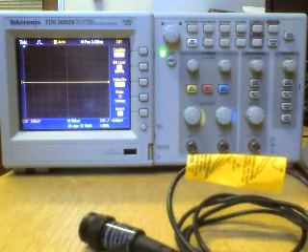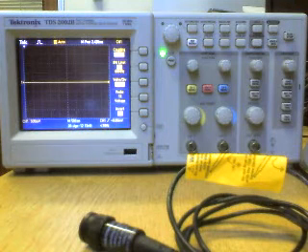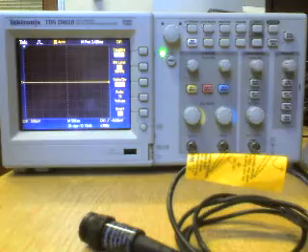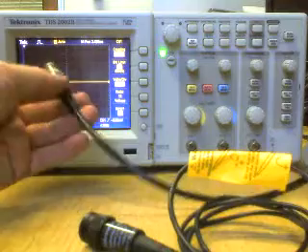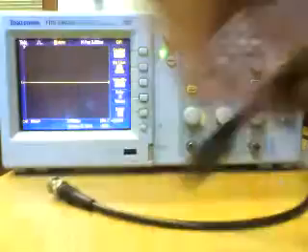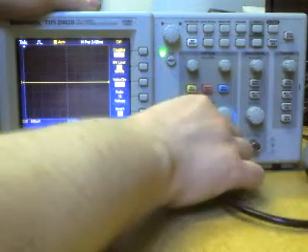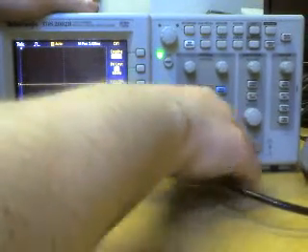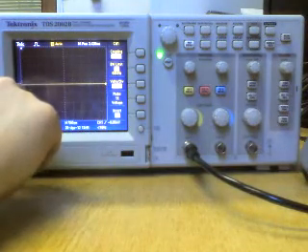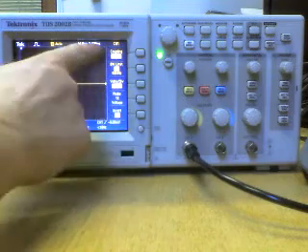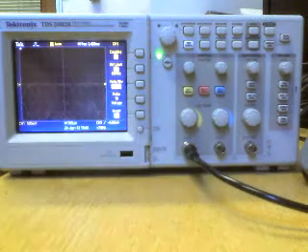Now then, measuring on your digital oscilloscope. Exactly the same way as on the analog one. The only difference is that the buttons and your values are in a slightly different place, so you just have to go looking for numbers, essentially. So we'll plug our signal into channel 1. Channel 1 is on, it says channel 1 here. It's currently 0 because it is grounded. It's around the centre of the screen, so we'll switch it on to first stop DC.